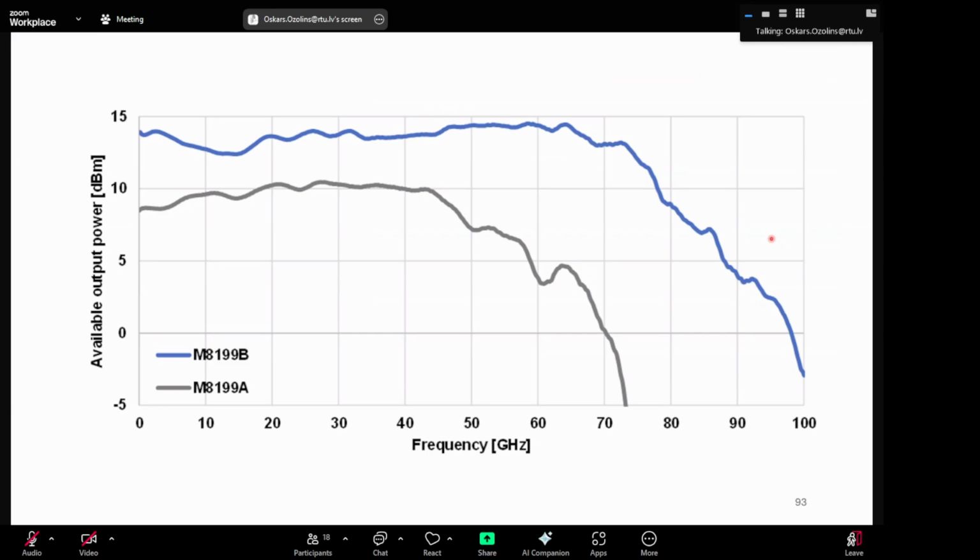Okay, so then there's another instrument which could be used to generate pulse amplitude modulation signals, not using this pulse pattern generator, where we combine two streams, delay one, attenuate the other one, and then sum them. Here I'm talking about the arbitrary waveform generator, called AWG. With that one can generate an arbitrary waveform, so you can basically generate even a sine wave with it, depending on which frequency you want.